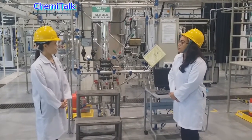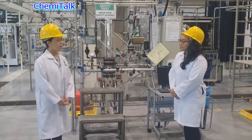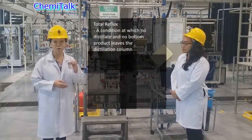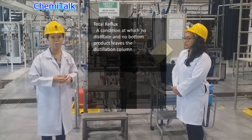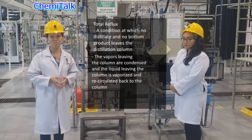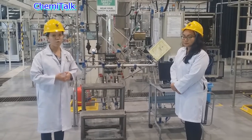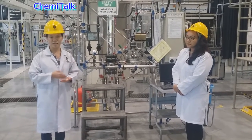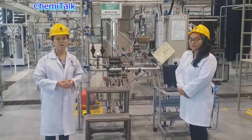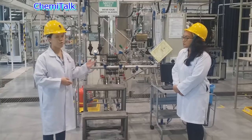Now we would like to proceed to experiment A that is being conducted. So what is experiment A about? Experiment A was carried out at the total reflux condition, where there is zero product flowing out at the top of the batch pack distillation column. All the distillate is recycled back into the column. In this experiment, we vary the heater power, which was set at 100, 80, 60, 40, and 20%. After that, the mole fraction of the ethanol is measured using the calibration curve that was developed from the previous experiment.